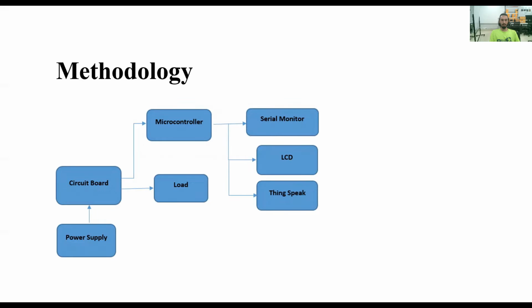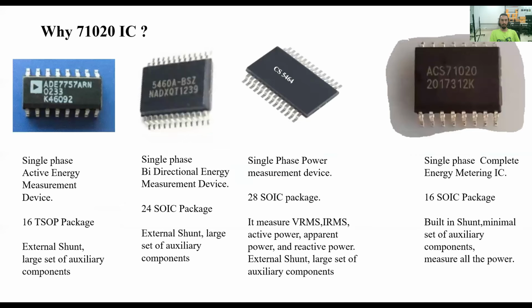This is the methodology of our project. Our circuit board, the meter, is connected with the power supply of 220 volts coming from WAPDA, and the circuit board is also connected with the load and microcontroller. Wemos is used in the place of the microcontroller, and the outputs are displayed on the serial monitor, a 16 by 2 LCD, and ThingSpeak.